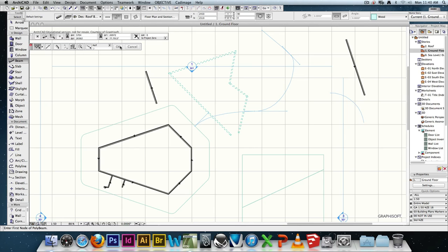So that's why you'll see that the beams are a dotted line. They will change. If you put them down lower, there is somewhere hidden in there, which one day you will see, a value of where that line gets drawn. Same thing like sloping walls. It has to cut through at some point. By default, I think it's 1.2 meters or something like that. So if you had an angled wall, you'll see where it cuts through, and they'll have dotted lines above that point and a solid line below that point. So just keep that in mind. Sorry, that was a little bit off topic.